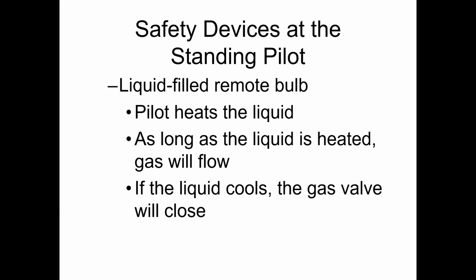So the garage and those mud rooms that are near the exterior of the house, especially a garage, can have air that is especially cold. You can have wind rush in when someone opens the garage or even the door, and that cold wind blows in. If it's a really windy day or something like that, it can blow out a pilot, or it can just reduce the temperature of the liquid enough. If it's really cold, it can reduce the temperature in the liquid bulb so that it shuts the pilot off.